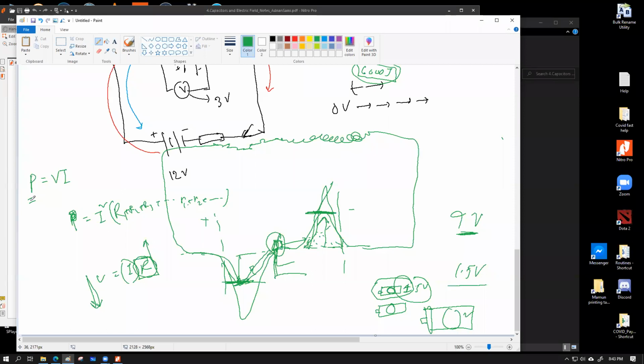The benefit of having a battery connected in reverse direction is, one, whenever you connect a certain battery in reverse orientation with a bigger source of the battery, a bigger voltage source, you can charge up that battery by reversing the chemical reaction within the battery. But the battery has to have that reversible chemical reaction compounds within itself. I mean, for example, you cannot use a regular sunlight dry cell to be rechargeable because they are made from ammonium chloride, which actually goes out into the air as ammonia gas coming out of the battery in a very small amount. We never smell that.